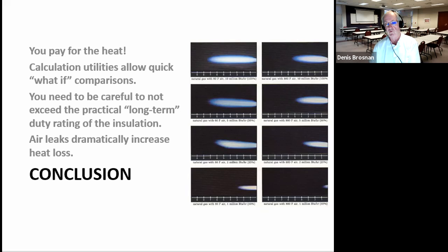So I like to use these utilities because it's really easy for you to answer the what-if question. It's really easy for you to model the furnace. And so the next 3 lectures are going to be furnace models. We're actually going to start with a heat treating model because it's pretty easy to understand. We're going to calculate the heat required by the load to get up to a certain temperature, and we're going to hold it at a certain temperature using the furnace heat loss utility.